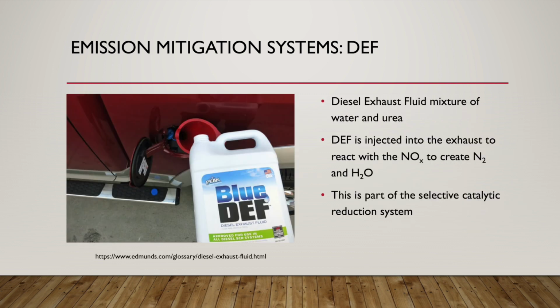The next emission mitigation system that I'm going to talk about is DEF. DEF is diesel exhaust fluid. This is a mixture of water and urea, and what it does is it works with the selective catalytic reduction system. For the SCR to work, you need the liquid reducing agent to reduce it.